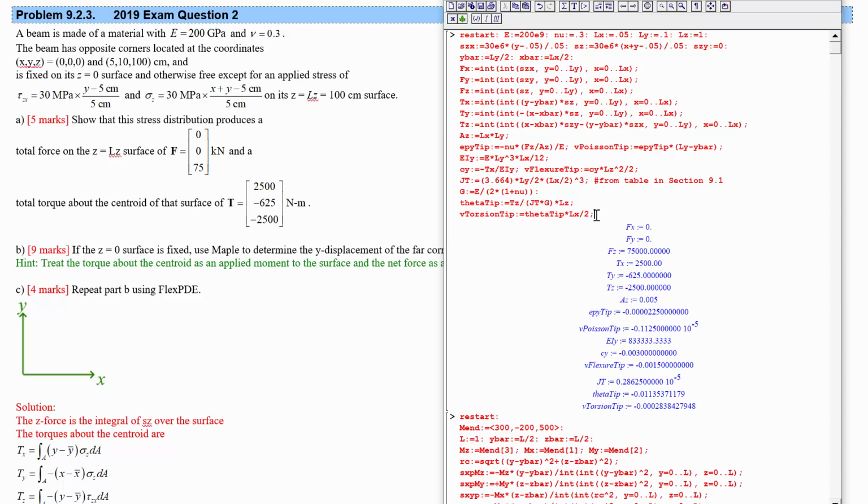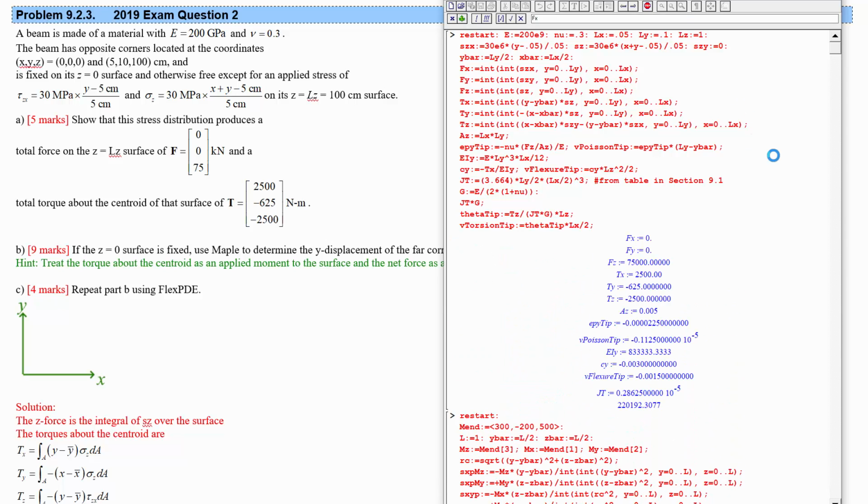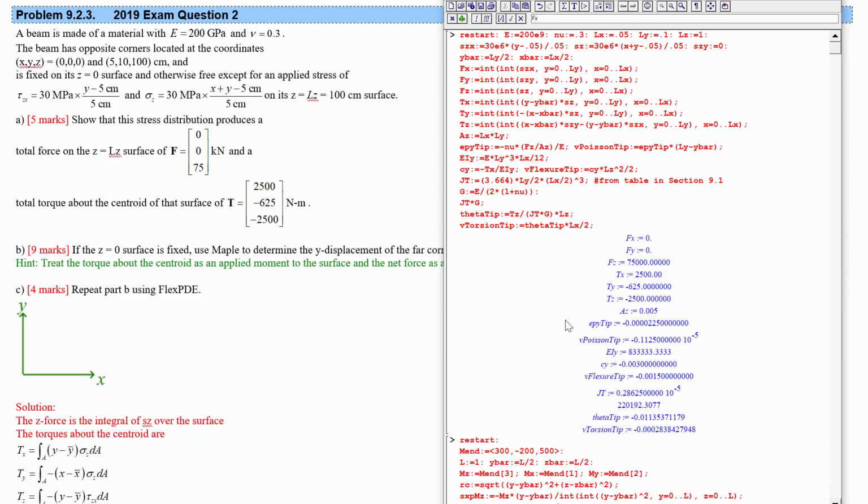This is kind of wide in y compared to how it is in x. So it should have had not so large of a torsion constant. Torsion constant times G. Let's work out what that is. So how big is JT times G? This will be the thing that we're outputting here right before theta tip.